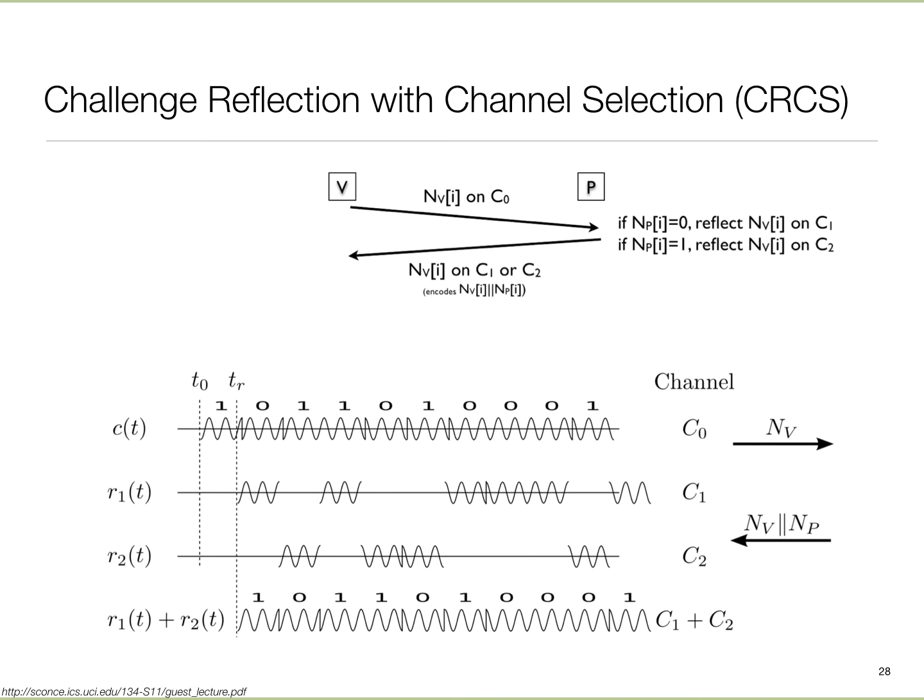So I have access to 2 radios conceptually. I can send out on one or the other, and which one I'm going to send out to will depend upon what the value of this is. So in a sense, I'm sending some waveform over C1 or C2, but which one I send out depends upon what the incoming bit was. So it's a little bit like XOR, right? One way of thinking of XOR is kind of as a multiplexer function. So that's basically what we're doing.